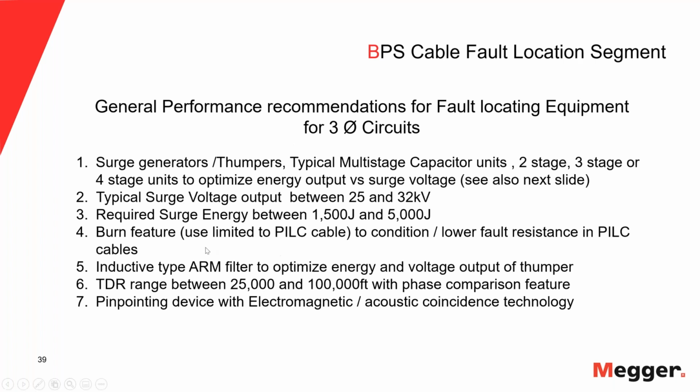Okay. Burn feature. Many people swear by burning faults, and a little bit of caution needs to be applied, because if I burn solid dielectric cables, I normally shoot myself in the foot. When you burn a solid dielectric cable, you set the whole insulation material on fire, which means it smokes away, and afterwards you will not be able to thump that fault anymore.